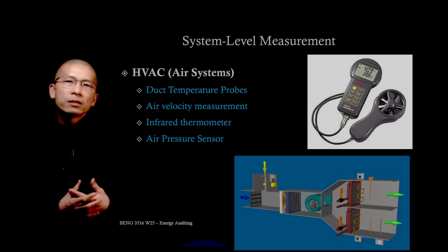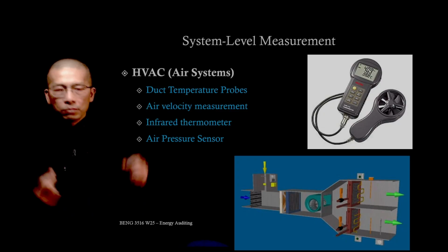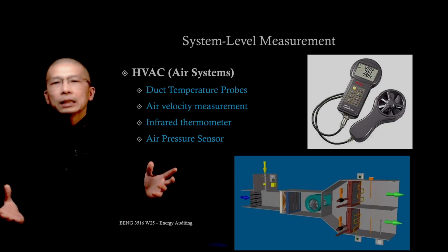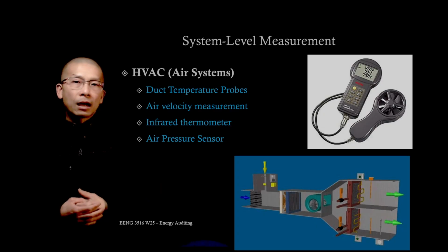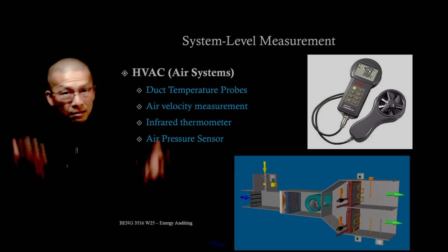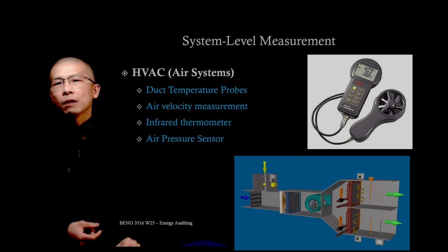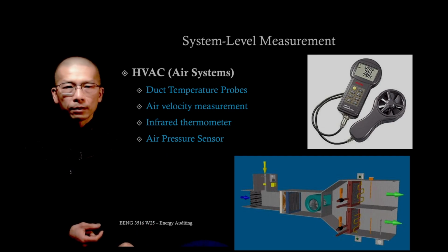The measurements help diagnose any blockage or leaking duct, and are essential when balancing supply and return air for efficient operation.